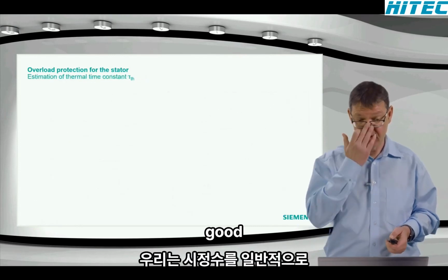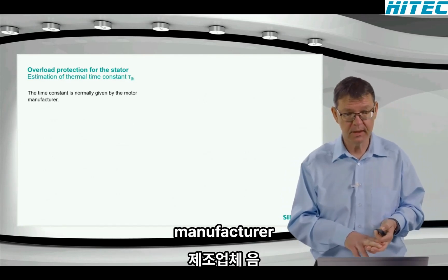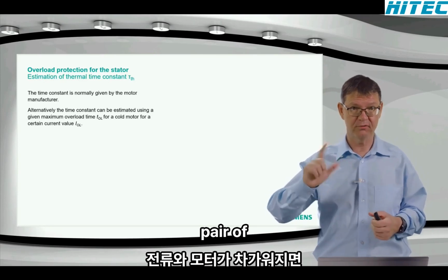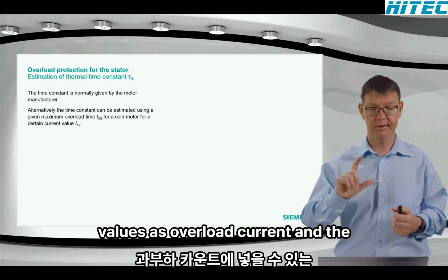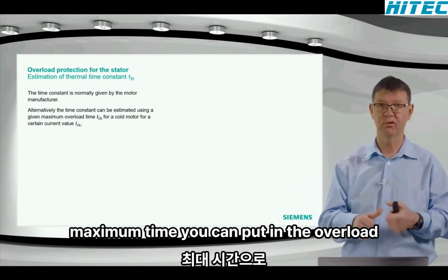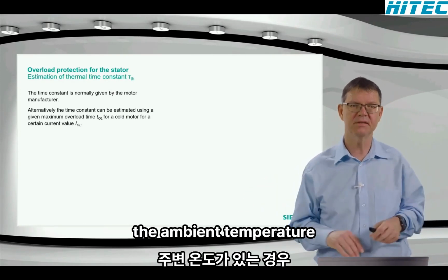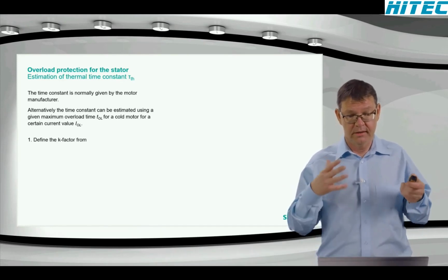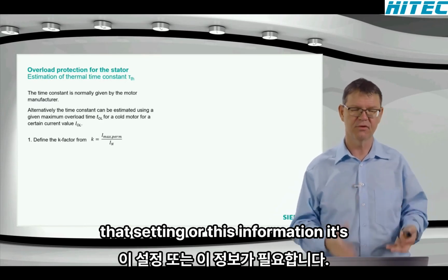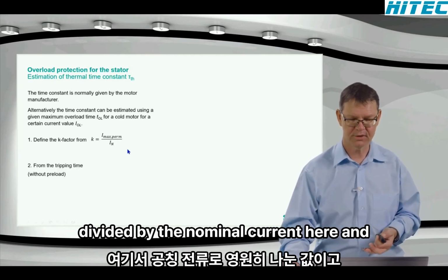Good. We can estimate the time constant. Normally you get it from the motor manufacturer. If not, then you might get maybe one pair of values as overload current and the maximum time you can put in the overload current if the motor is cold. So if it stands still and it has the ambient temperature. The K factor we get, again, we need that setting or this information. It's the maximum permissible current forever divided by the nominal current here.